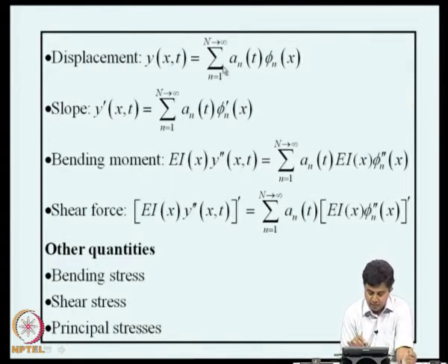Here the summation should run from n equal to 1 to infinity, but typically in numerical work we stop at some finite capital N, and the rate at which this series converges is different for displacement, slope, bending moment, and shear force. Typically a lesser number of terms is needed for convergence of displacement, and a higher number of terms is needed for shear force.